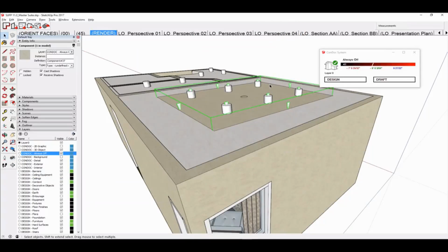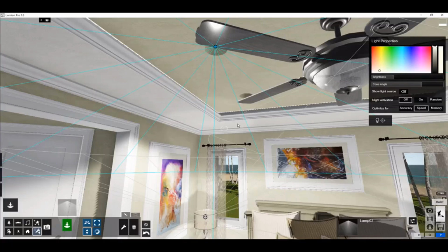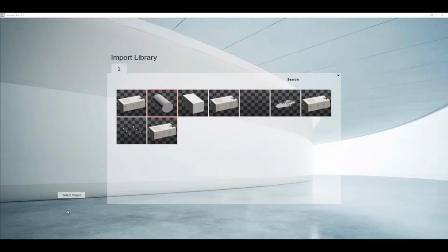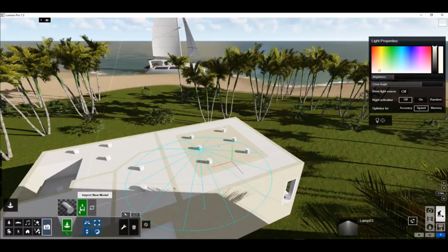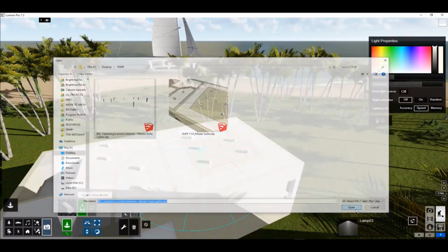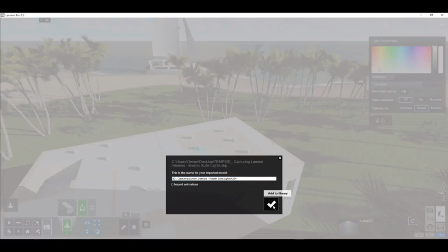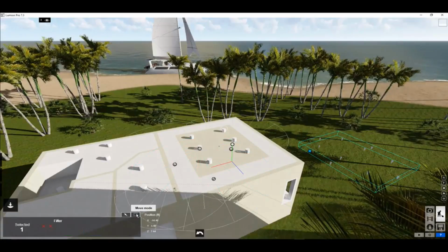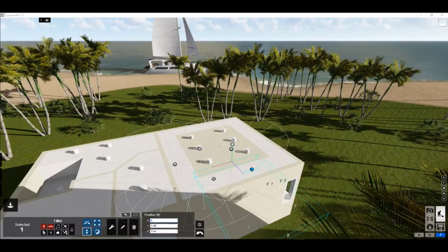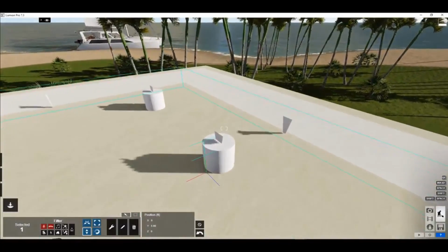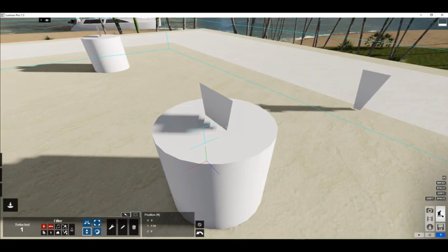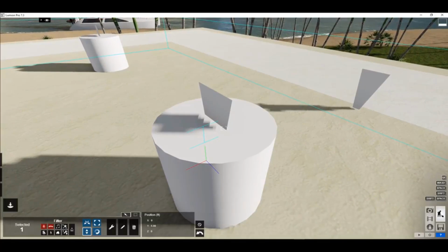Now what I can do is go back into Lumion in build mode. I'm going to go to my place mode, and we're going to place a new import. Here's my lights. I'll choose open, give that a different name, say okay, and then click to place them. Immediately then go to move and choose 0, 5, and 0. See, now those all line up. This is why it's so important to set your model at a known origin point, because it makes patching in these other pieces effortless.